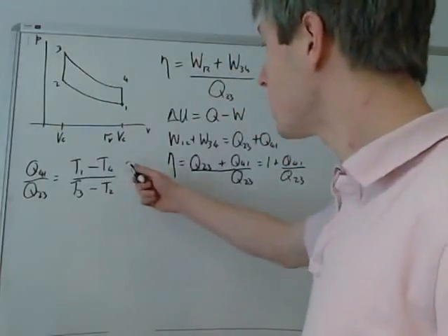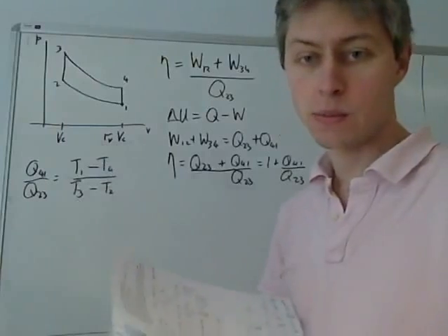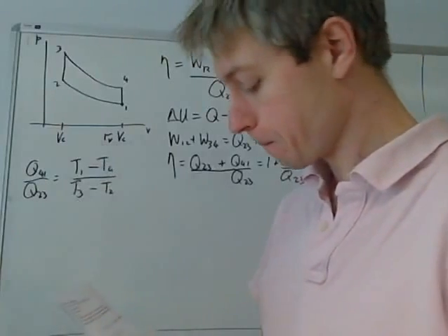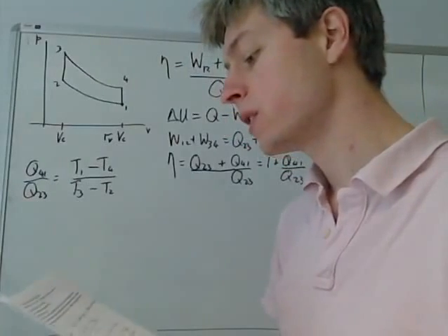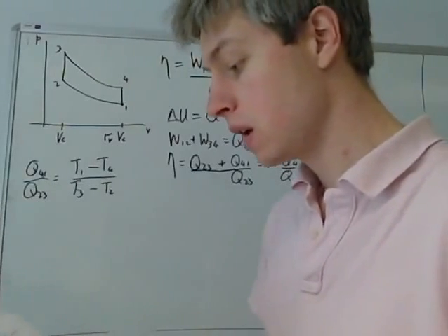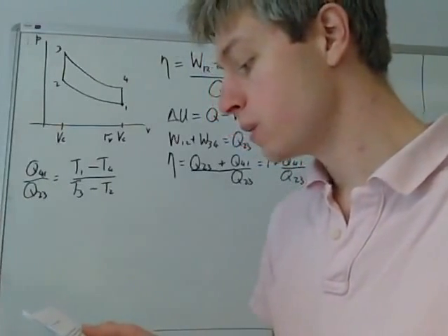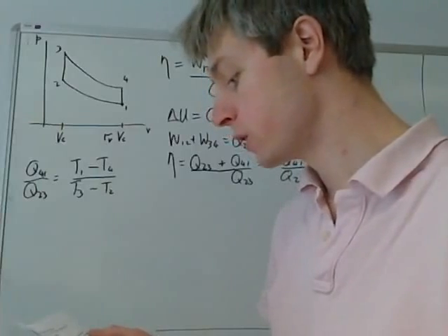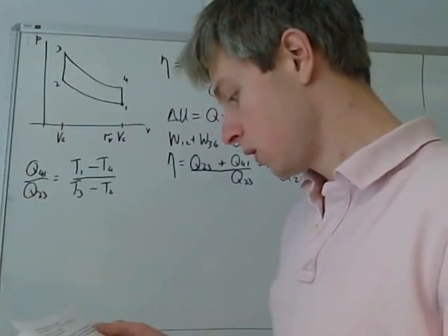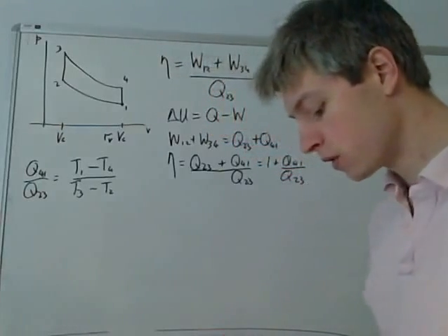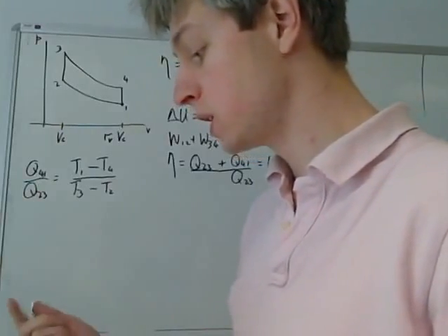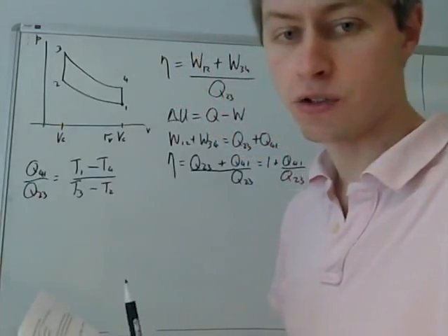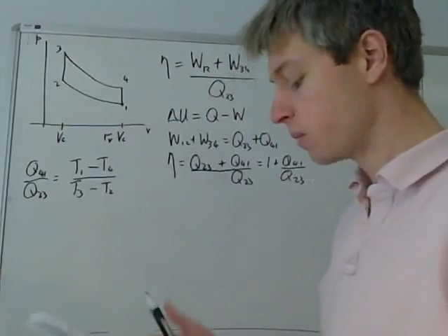Right. So now we can answer the problem in terms of temperature. And working around the cycle, we have various isentropic processes. We only know the initial temperature and pressure, but we do know the volumetric compression ratio. So we want a relationship between this volumetric compression ratio and the temperature changes during the isentropic processes.